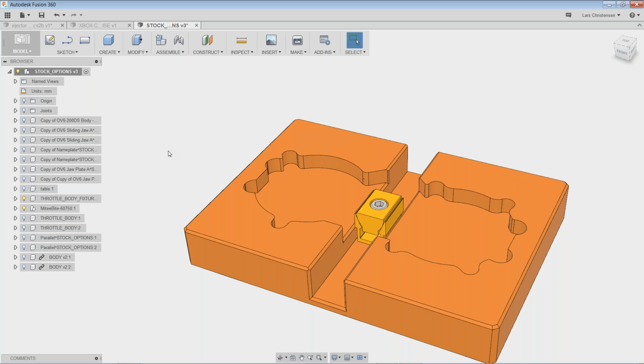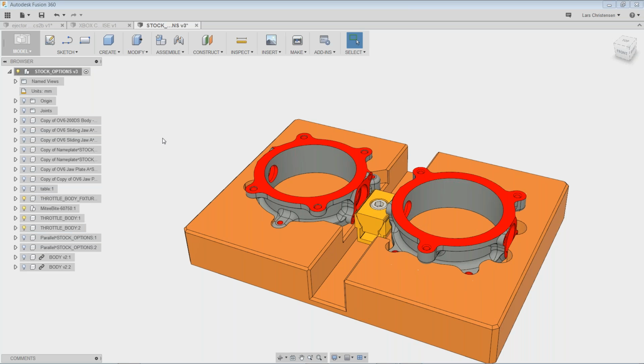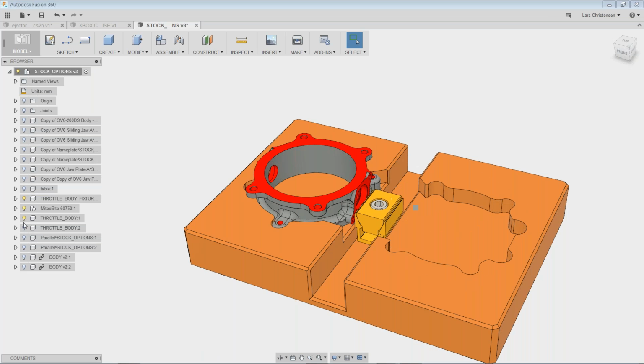you could machine. You could put the aluminum block in the vise, machine this part here, and then you could put the two parts in to do whatever machining you have. Maybe these parts were cast or something else, right? Sometimes you get parts that you don't have to start from scratch, but maybe here you have to face them off. Maybe you have to drill a couple of holes in these parts here.